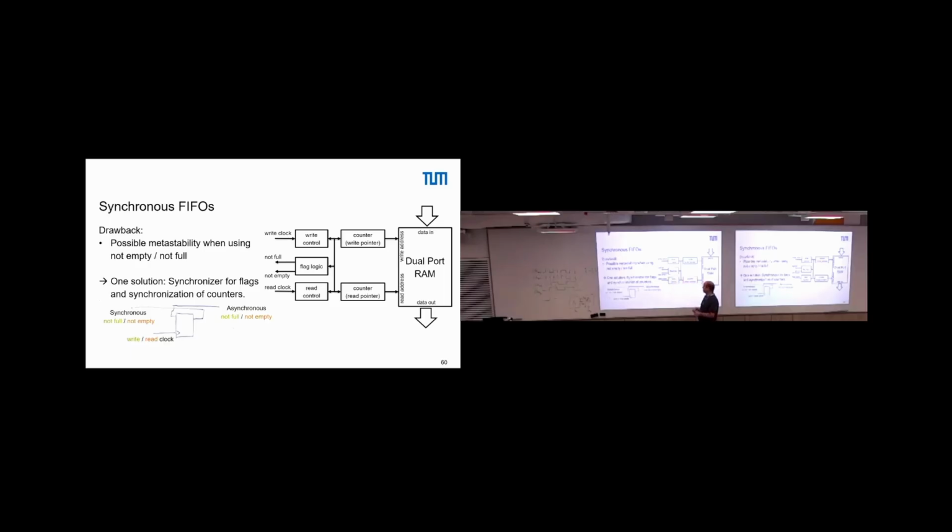Why is this? Because if you count, so let's say we have a binary counter. We start to count from, let's say we are currently at a 3-bit address, which is, let's say, 110 with one of our counters. Doesn't matter with which one. Then we increment. The increment is just 111, we add 1. We increment another time. Now, the outcome will be 000, the thing overflows, right?